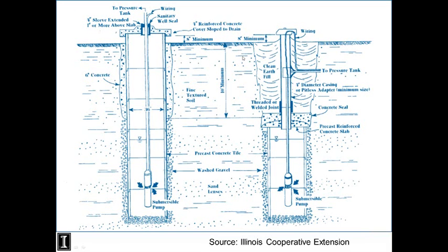Or in Illinois, they've changed the law now because of the potential for contamination of these shallower wells. The Illinois Department of Public Health requires you to have 10 feet of fill with a regular monitor cap that you'd have for a drilled well over top of where the well can take in water. So this is all clean earth fill material, so that it protects it at the surface, and surface contaminants can't move down through here, and your water bearing area is down in the lower half.